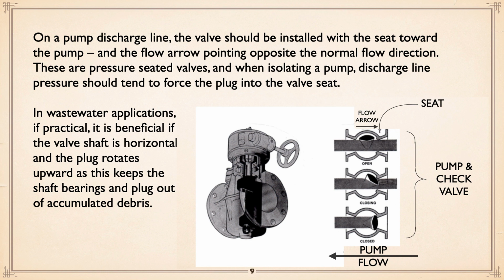basically you've got your pump over to the right, and you see the flow at the bottom is right to left, but when the pump is stopped, the pressure is the way of the arrow. So we want the seat towards the pump.